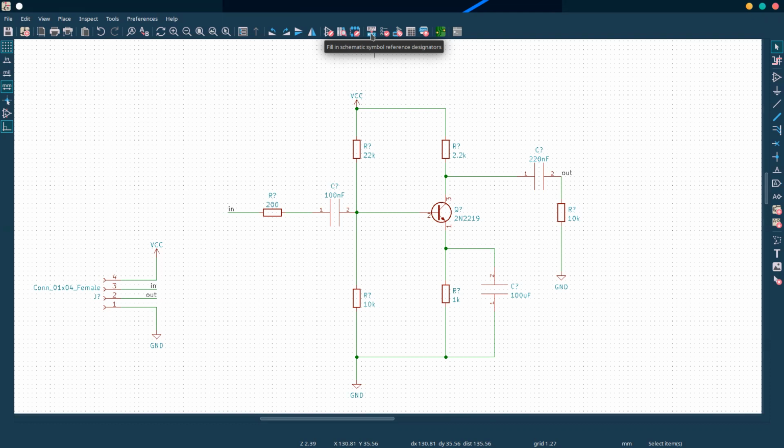Oh, so you do it that way. Yeah, you don't buy the component and then choose the footprint, you choose the footprint first. Well, you probably make sure you can get it before you put it on the PCB. Another thing to consider is that the team generally does hand soldering for basically everything. So if you're picking components that are 0.25 millimeters long, you're going to have to solder that, so it's good to pick bigger footprints where you can.